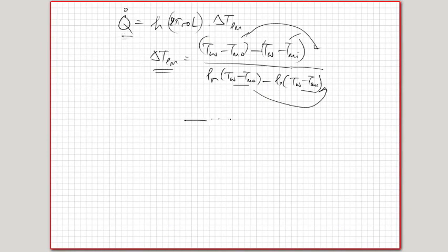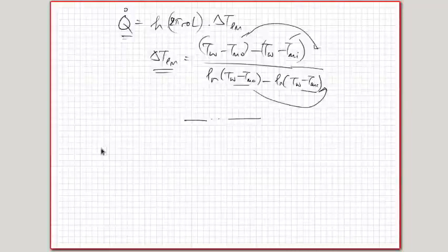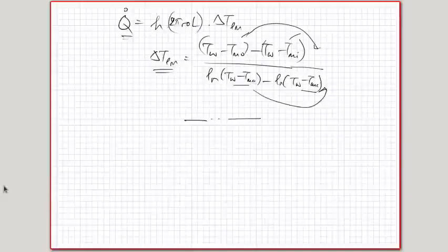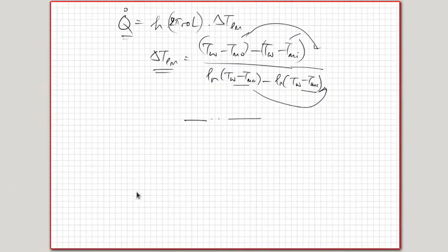This is something that is commonly used for heat transfer to a fluid that is heated using a constant wall temperature pipe when the flow is fully developed in the entire length. Of course, if h is not a constant, then it also becomes a function of x, which needs to be integrated along with the remainder of the expression. Then this becomes more complex. It doesn't remain this way. But this expression is valid when the flow is fully developed in the entire length, or you can assume that the developing length of the pipe can be neglected. Okay, so that is one part.